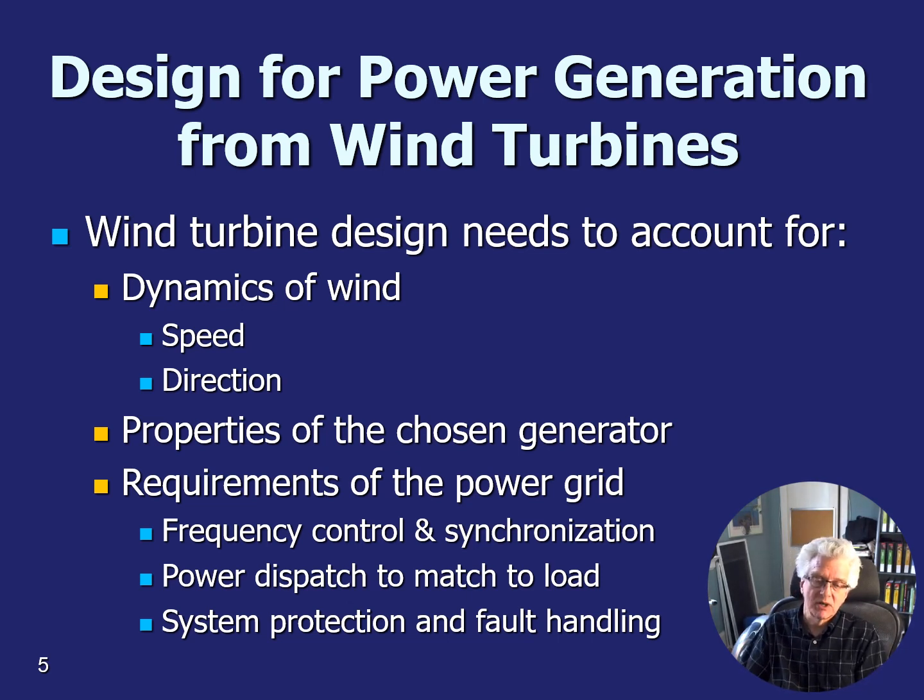The electronics of the generator have to work so that you can feed them into the power grid. You'll often have, at a wind farm, a local distribution collection network, and you can make your own choices about how to do that. But in the grander scale of things, connecting to a power grid, you've got to be able to do frequency control and synchronize with the AC sine wave.